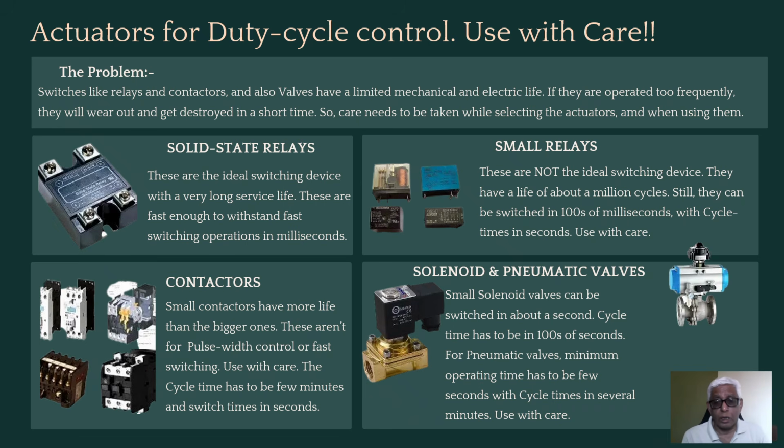So that means you'll have to factor in that minimum 20 millisecond minimum on time, because that is the cycle time for a single AC cycle. Half AC cycle, you can take it to be 10 milliseconds, let's say, and these things work very well with heaters.